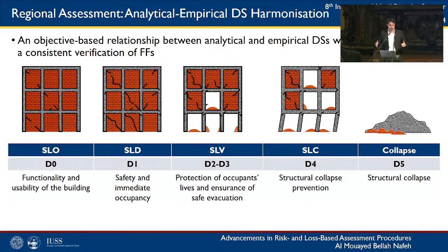As we pointed out, there are many different sources of these things. Obviously, quantifying and relating empirical and analytical can significantly influence whether our fragility functions are shifted left or right internally compared to each other. We believe that it does influence, particularly, for example, collapse analytically was considered as 5%, which is a big margin, obviously, but we just wanted to be sure that, okay, if we reach 5%, our numerical model is not going to resurrect. It's collapse.